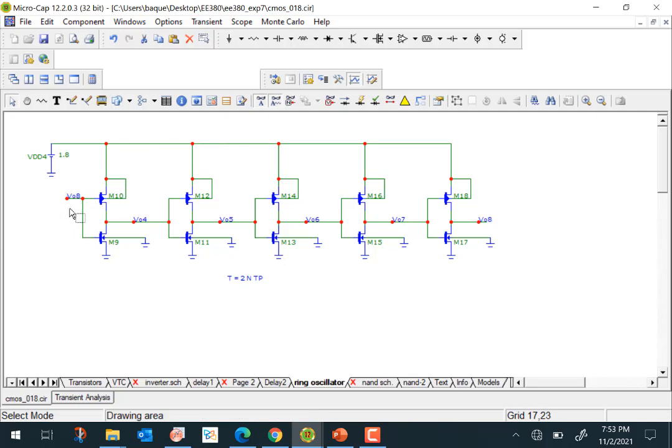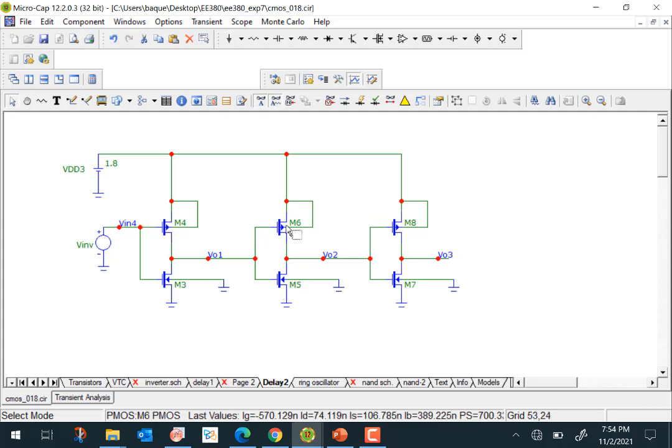Right, so you'll have to make an odd number here. So not exactly 32, but you'll have to make 5 or 7 or 9 or 11 like that. So try making a long chain of inverters and see how it behaves and measure the propagation delay by that means. And you can compare that propagation delay to the delay of the middle inverter that you measured here, and see whether it compares favorably or not.